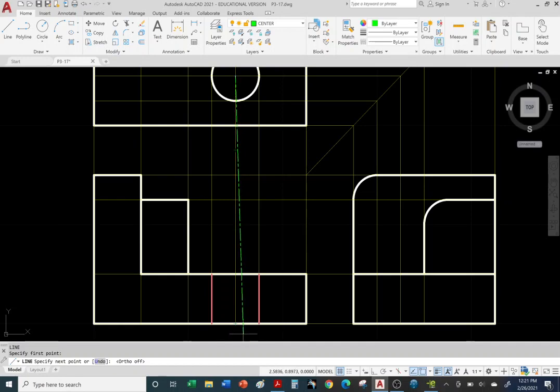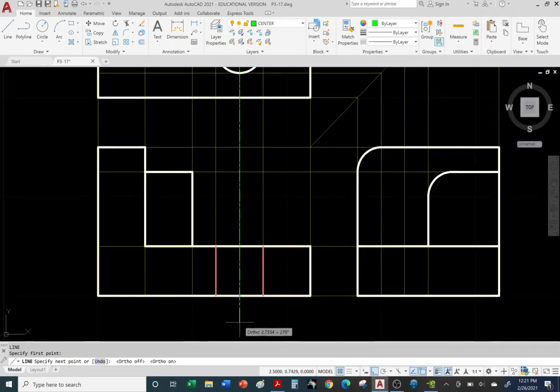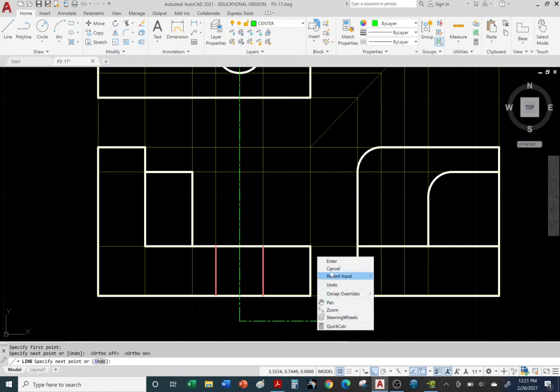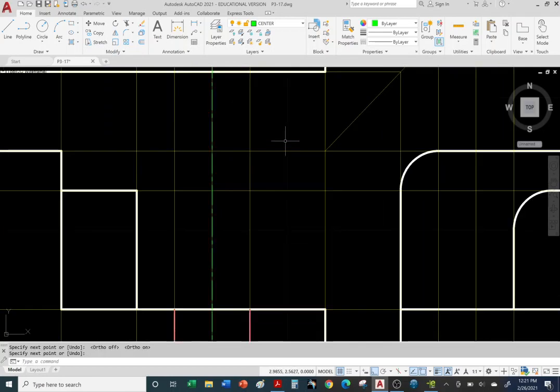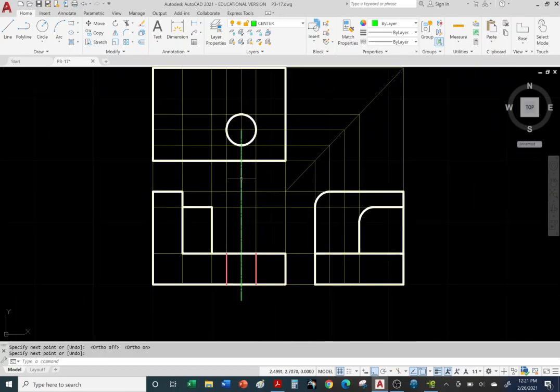And I'll be able to tell, right, when I open your file, if it's slightly off, I will take points if your line looks something like what we're currently seeing. Okay, let me turn on ortho to guarantee a vertical or horizontal line and go beyond the object line. How much? Just guesstimate. If you just go a little bit, it doesn't look as clean. It's better to actually overextend than to just slightly extend. Okay, so you can always readjust it and click. Okay, so right click enter to exit, or enter on the keyboard, or escape on the keyboard.